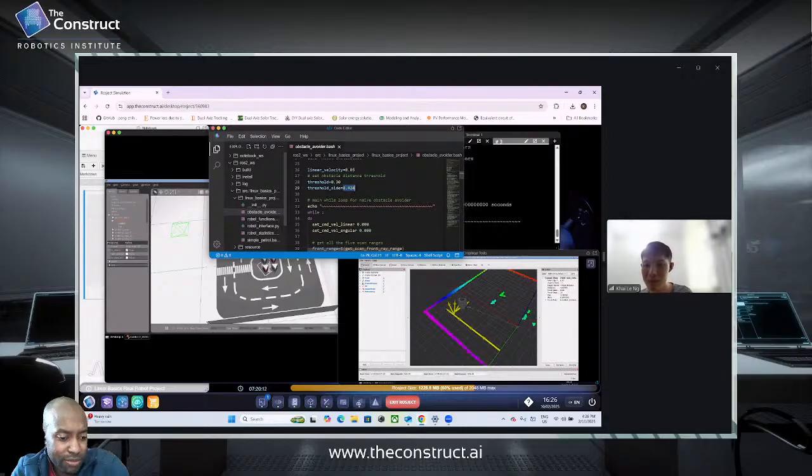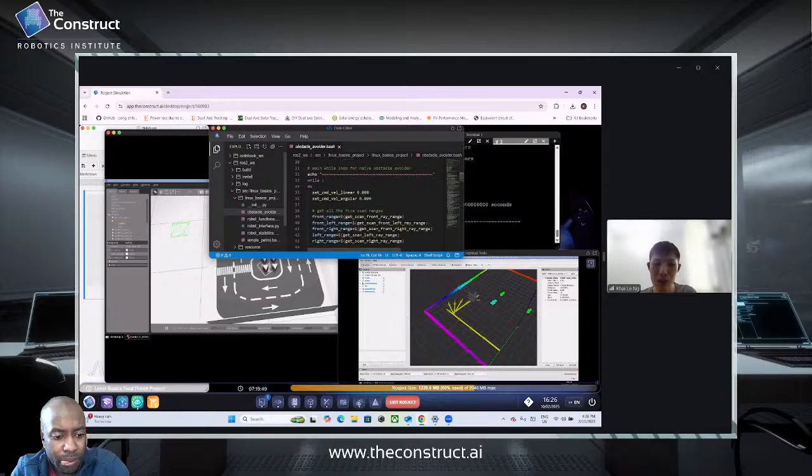But it's valid that you said when it gets to 0.3 it will be too close. So for now I can't take your word for it, but let's go. For the virtual robot it's actually too far, but when I run the real robot it's actually too near. So that's why I set a greater range for the front left and front right.